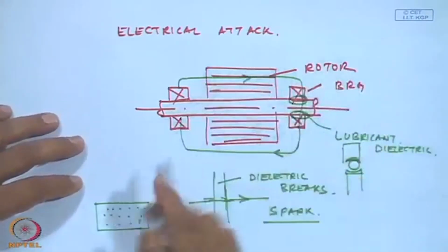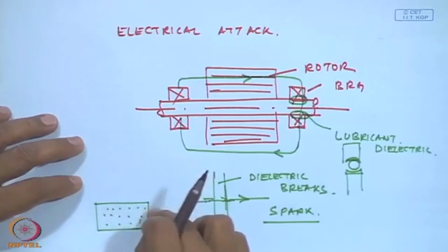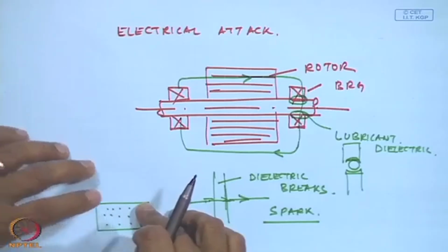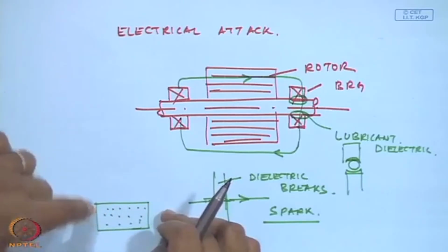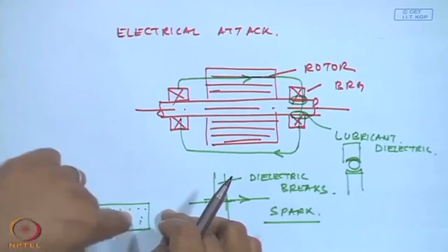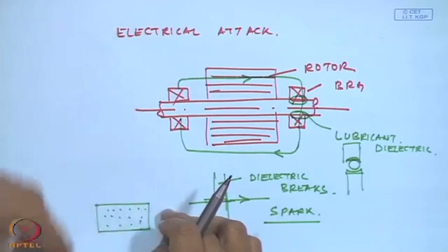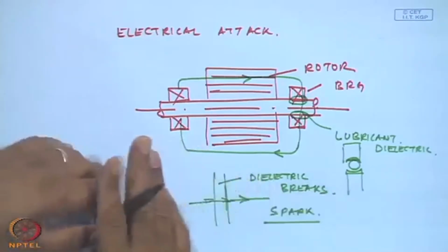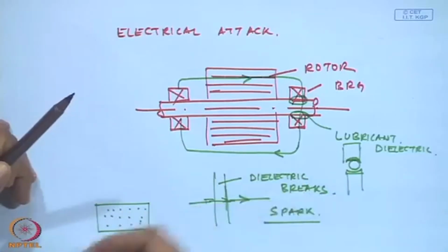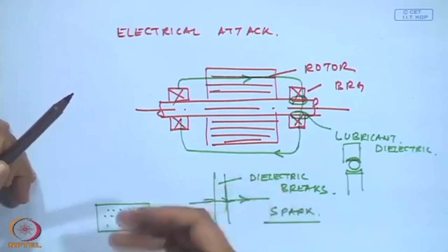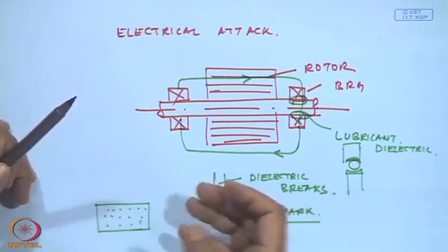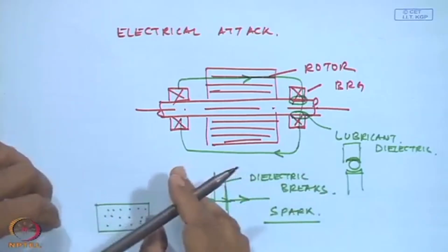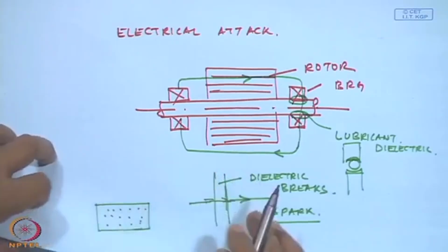But these are responsible for the initiation of the pitting. Once the surface has got pitted, because of load and temperature they are weakened, and then with time this small pitting will become large, and spalling will occur, and then large chunks of the material are going to get eroded. So, surfaces are going to get worn out again.